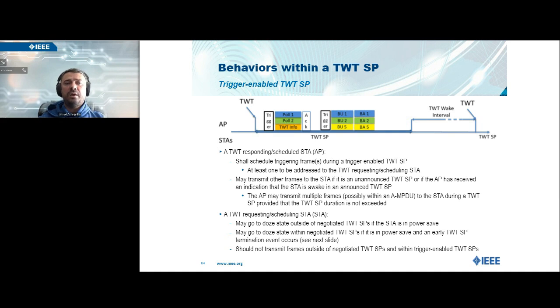And then eventually also provide a buffer status report for their uplink so that the access point, with that first phase of polling, can determine the availability of the station in that service period and how to allocate the resources to that station or also to the other stations that are awake in that service period.